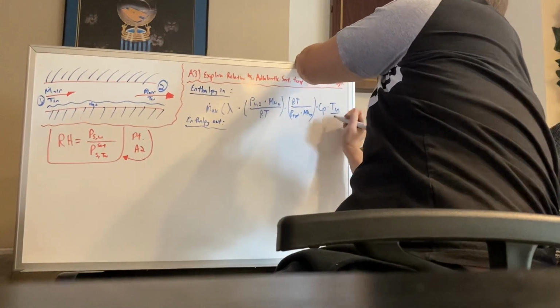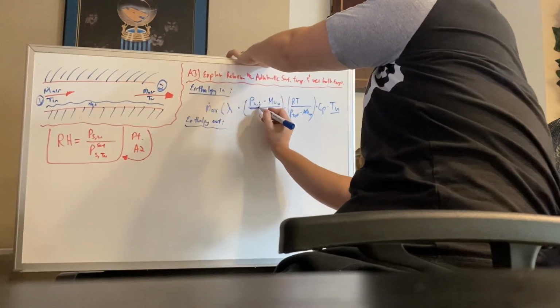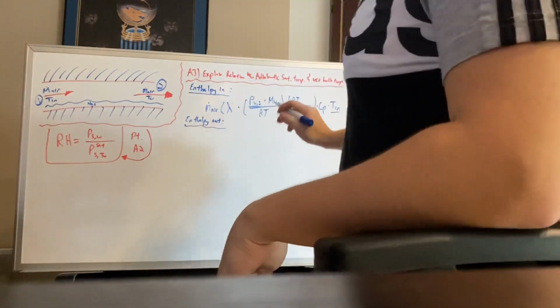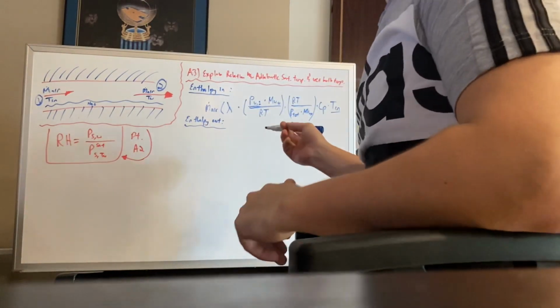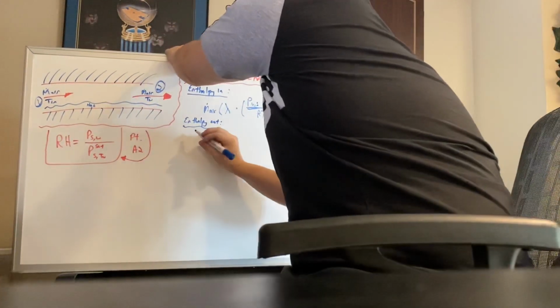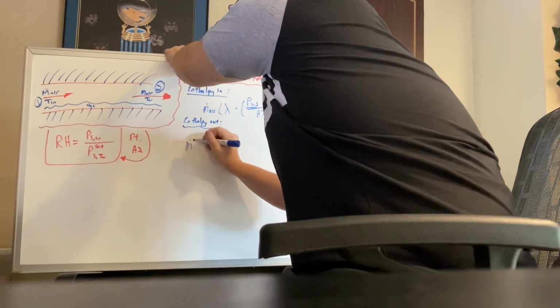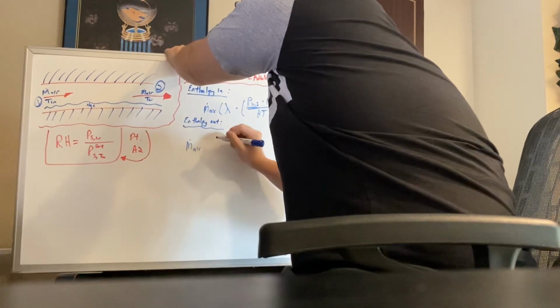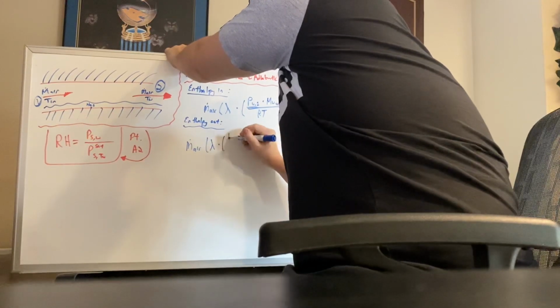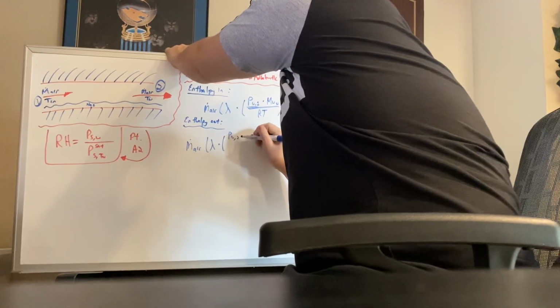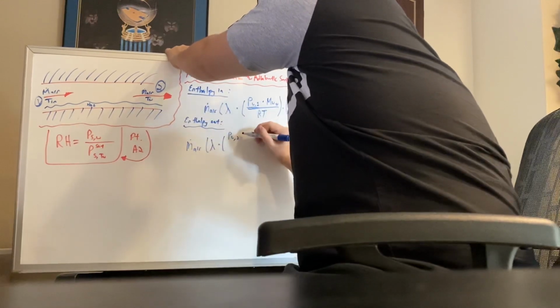So this difference and this difference here are the two that will be differentiating between enthalpy in and enthalpy out. In reality, the enthalpy out is pretty much the exact same equation: the mass flow rate of the air multiplied by the heat of vaporization. The only difference is that we will be looking at the partial pressure of water at the second location at the end of the pipe.